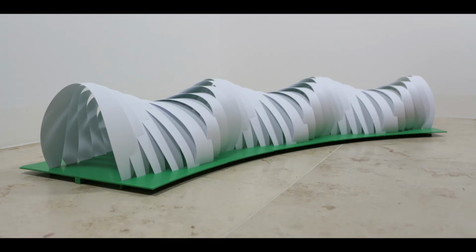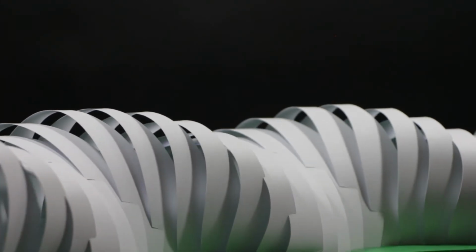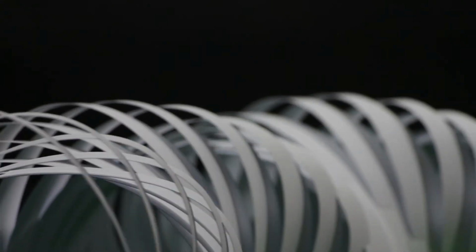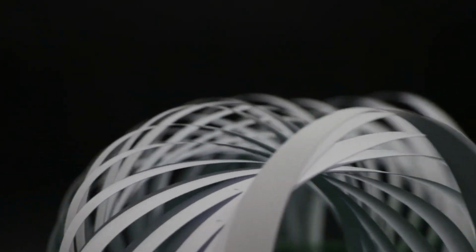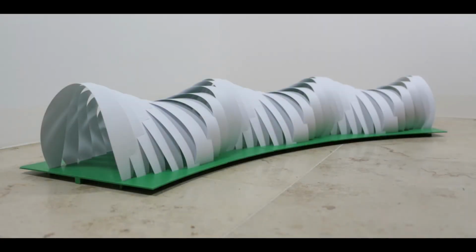We can use the linear program to design simple structures in active bending, such as this one. This model is about 1 meter long and is composed of 31 arcs. Each flat element is cut from cardboard and then curved by inserting it into a 3D printed base that has indentations to enforce the boundary conditions.